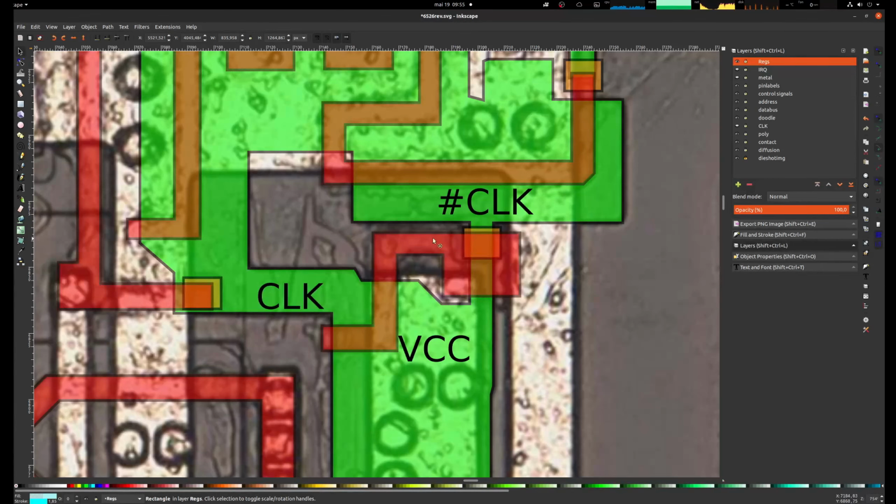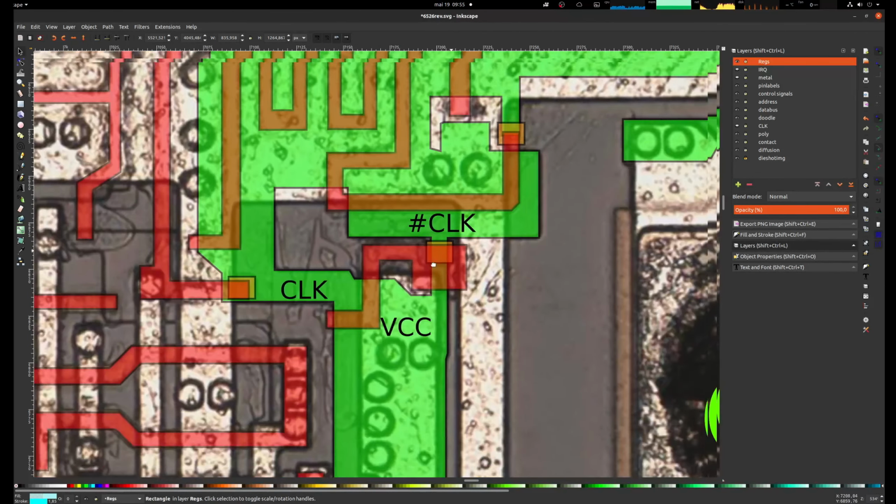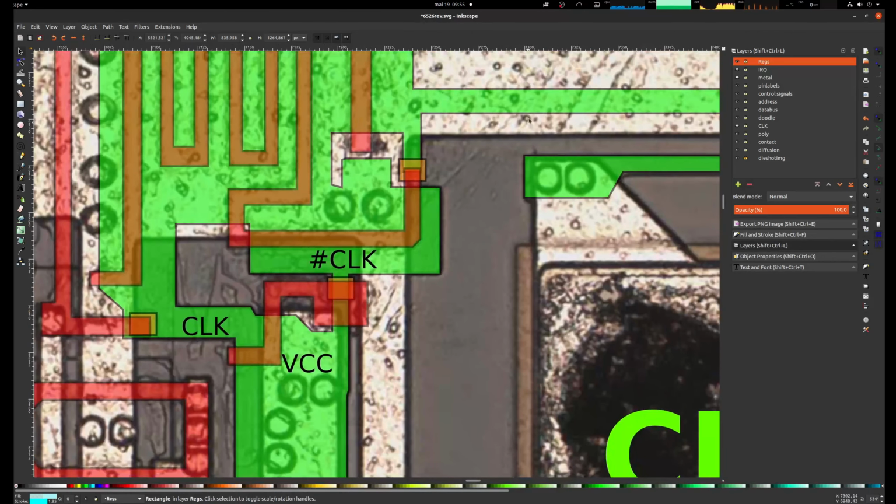However, the output of that pull-up is amplified here, sort of. We can just have a quick thought experiment here. So if the input is high on the clock, it will pull this one to ground, right? But it also pulls the pull-down to ground. Therefore, the line here, the poly, will also be at ground.